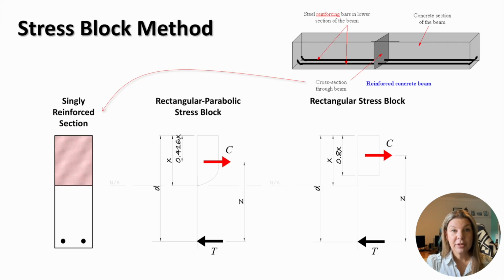Eurocode 2 defines the principles for design of reinforced concrete structures, which allow for certain variations in design procedures. As we previously discussed, the design of a singly reinforced concrete section for the ultimate limit state can be carried out using different stress-strain diagrams for concrete in compression, including parabolic-rectangular, bilinear, and rectangular diagrams.